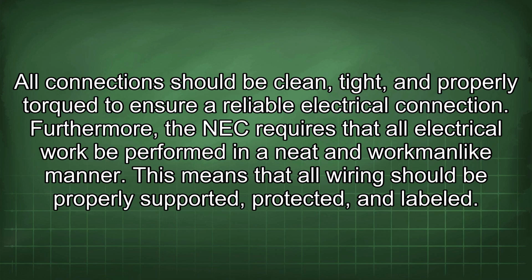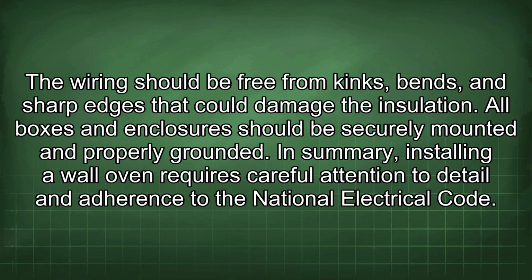Furthermore, the NEC requires that all electrical work be performed in a neat and workmanlike manner. This means that all wiring should be properly supported, protected, and labeled. The wiring should be free from kinks, bends, and sharp edges that could damage the insulation. All boxes and enclosures should be securely mounted and properly grounded.